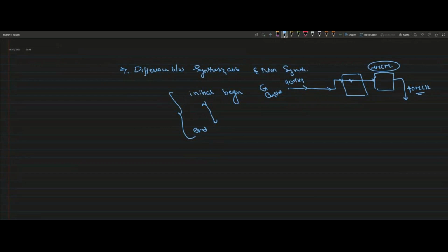So can you tell me how you are going to write the logic for generating the 10 millisecond delay? You mentioned a counter, so can you just tell me how you are going to write that logic? Forever and all will not work actually. That is also a non-synthesizable construct. Forever is used only for simulation, for clock generation, right?